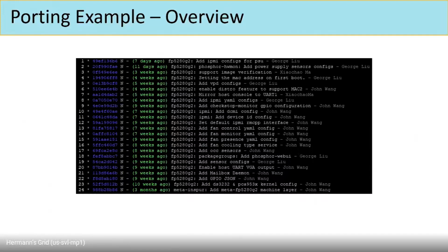It's generated from the MRW, which is the machine readable workbook, to a report file, which defines a list of all the IPMI sensors. So I have a utility to convert that report file to the YAML config. But that is not mentioned in this talk. If you are interested, we can talk later. Okay, thank you.